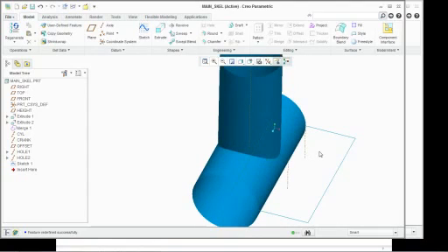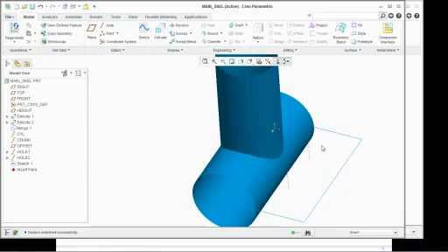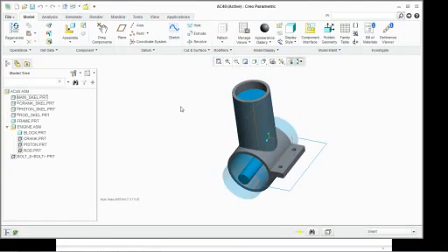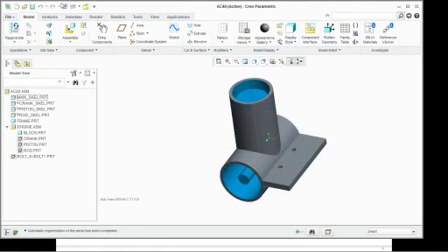Instead of having to go back to an engineer and say, hey, I need you to update that entire assembly, I can simply go in now to my assembly, and if I update my assembly, notice the parts update with the skeleton. So you've got all those critical dimensions you need right there at the very beginning in that initial skeleton, and when you update that, you can change the overall function of an entire assembly without having to go in and edit specific components.